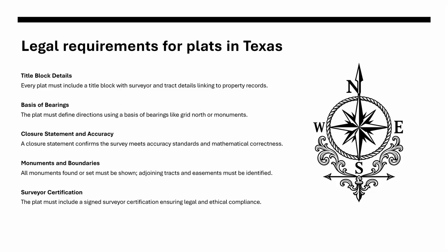Third, the plat must contain a closure statement. This demonstrates that the survey meets board accuracy standards, typically 1 to 10,000 for urban surveys and 1 to 5,000 for rural surveys.